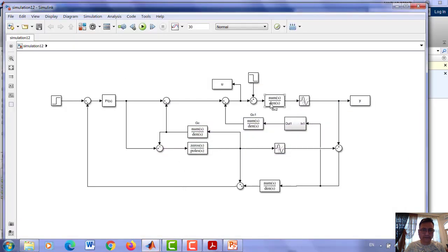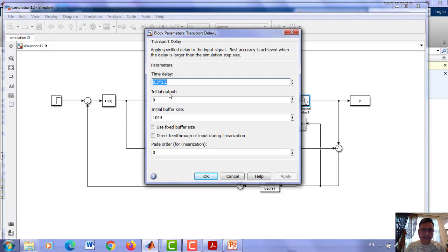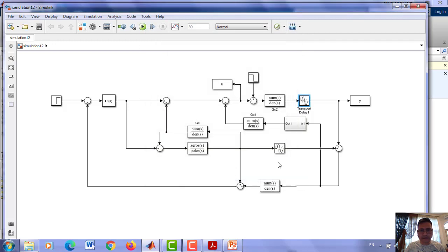Here the difference is the time delay is changed from 1.3 to 1.1 to increase that, and the gain is changed, and from here we can see the output. Both the process gain and time delay are increased by 10% and each of the time constants is decreased by 5%. To check the system robustness, the system outputs and control signal under mismatch condition are shown.